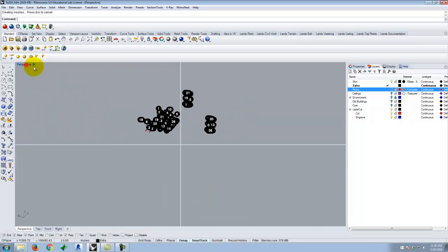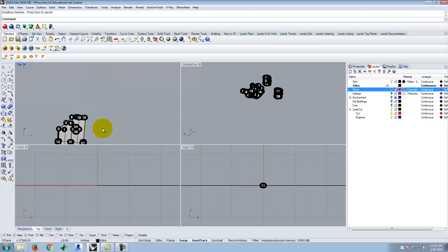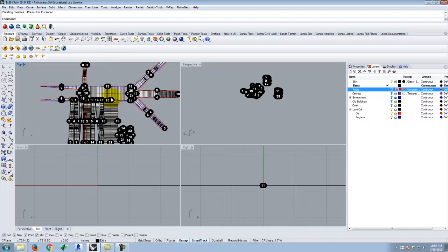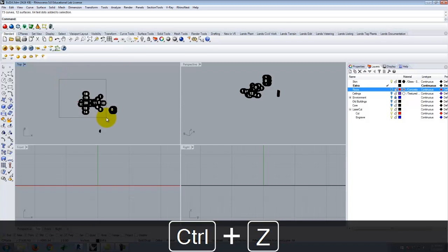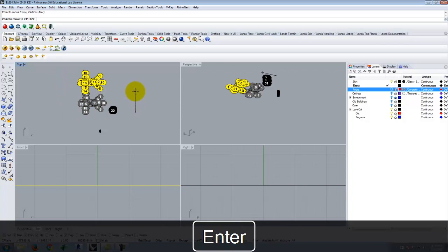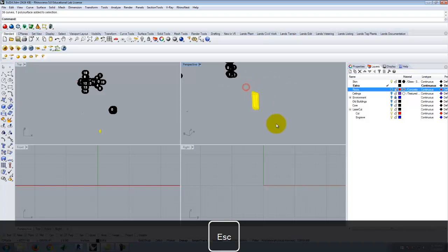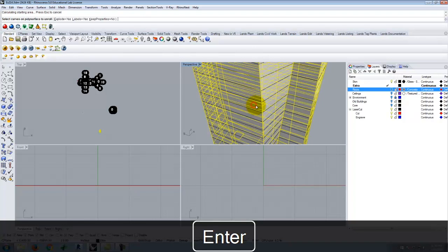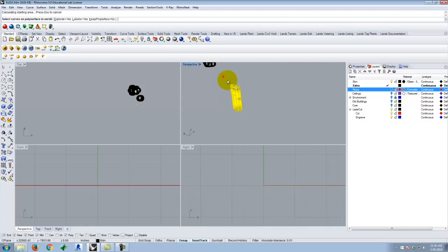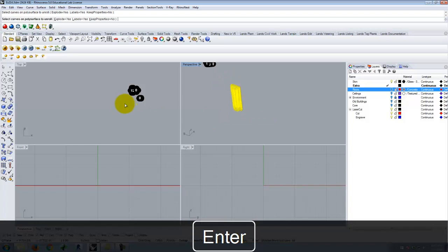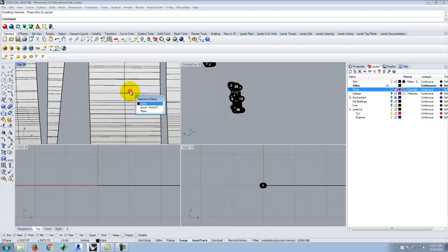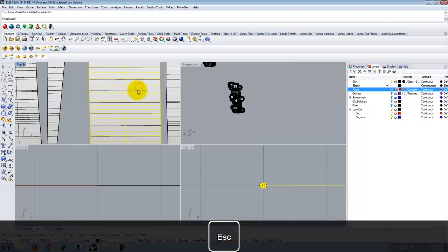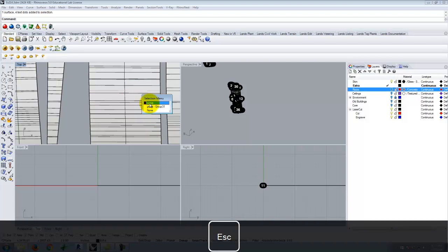And if we look at it in the top view, somewhere, it's on top of my other one. Right? Let me back up 1 second here, and let me move this one out of the way. Yeah, it goes to the origin. And let me do that again. Unroll surface. Surface first. Select curves as well. I'll select the curves, and I'll go ahead and hit enter. And so here they are. Now, we have the surface, but we also have all of the individual little curves that unrolled with it.